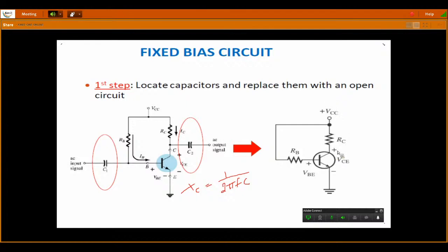So plus VCC we are connecting, a positive DC signal, to the collector terminal. The collector terminal is of N type, hence the output junction becomes reverse biased. So your transistor is operated in the linear region. Now with this applied VCC, RB and RC, we are making an input current transferred through the base region, and we will collect the output collector current, which is IC.